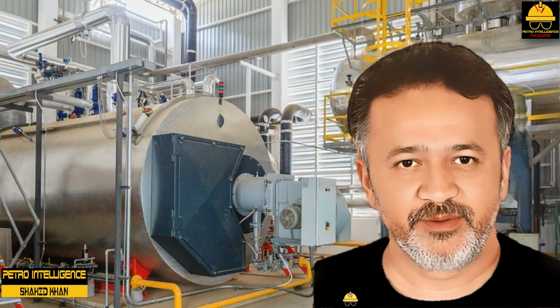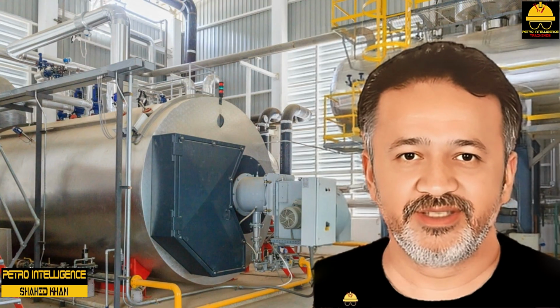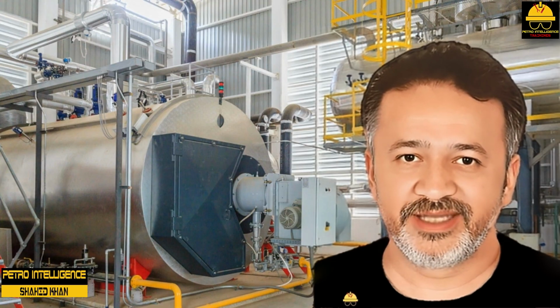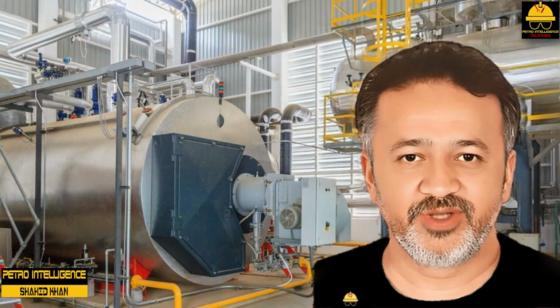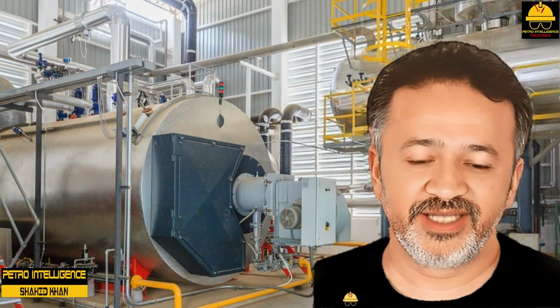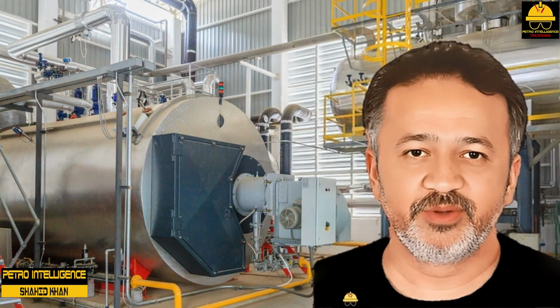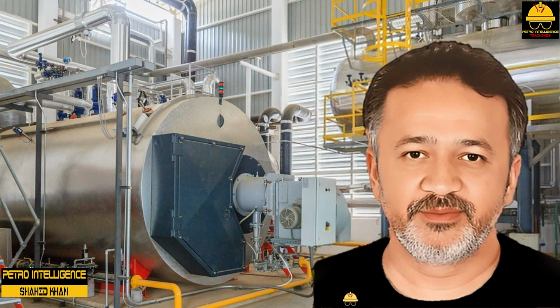The most common type of large commercial boiler is the watertube boiler, which consists of a furnace that contains an upper and lower drum connected by tubes. Circulation through the system depends on density differences in the water in the various tubes. This type of boiler produces superheated and desuperheated steam.